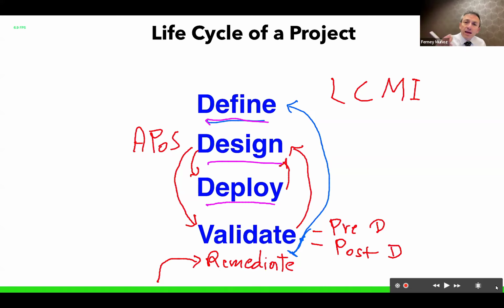Then when you place an AP in design, it uses that data. If I place that AP here without you drawing any walls, it knows that in the survey, when I measured here and there, I lost 10 dB. So there must be something there, a door, a window, or whatever it is. You lose 10 dB in this area, so if you place a simulated AP here, when I go through that area I'm going to remove 10 dB, and then it's going to do all the heat map for you.